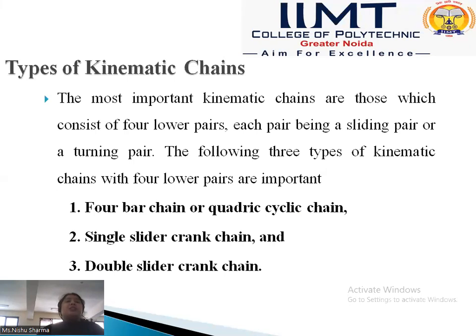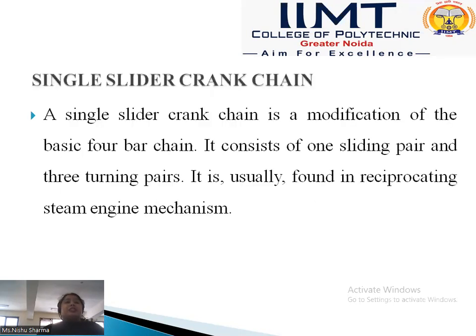Now we will discuss the single slider crank chain and the inversion of a single slider crank chain. The single slider crank chain is just a modification of the basic four-bar chain. It consists of one sliding pair and three turning pairs. It is usually found in the reciprocating steam engine mechanism.